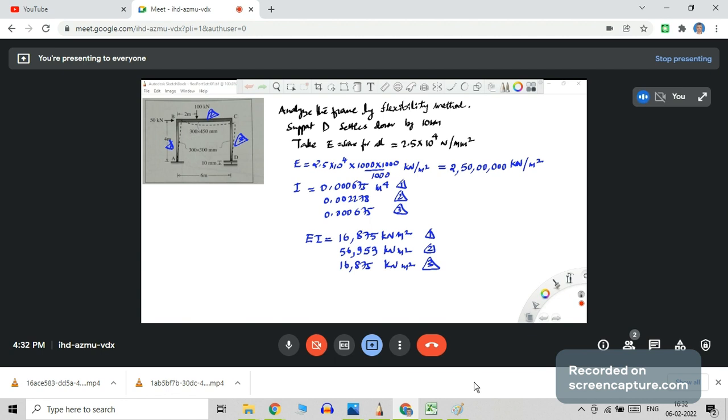And in this problem further, you need a primary structure that is statically determinate. We have two fixed supports, three extra, DS equal to 3, so we need to remove three reactions, so three redundants. So it is preferable, and our earlier objective will also be achieved, if we remove support D to make the primary structure. That's a fixed support D, so we have various reactions including the vertical reaction.